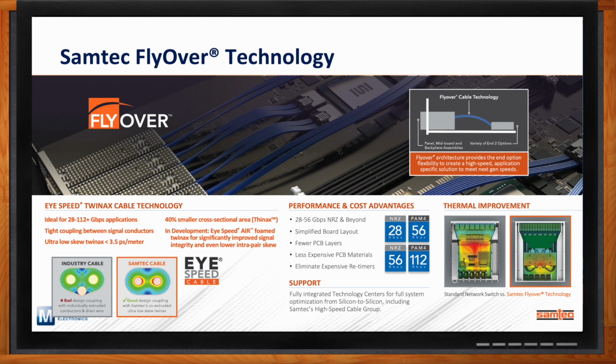However, by getting rid of traditional PCB traces, routing the signals from the ASIC to the Twinax cable, you can move the ASIC farther back in the system, closer to the thermal management devices, and that big red spot over the ASIC is removed. So price competitiveness, thermal enhancements, lower power, overall FlyOver architecture is really redefining system architectures within the data center and also in the embedded ecosystem as well.